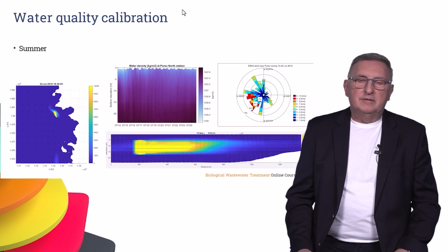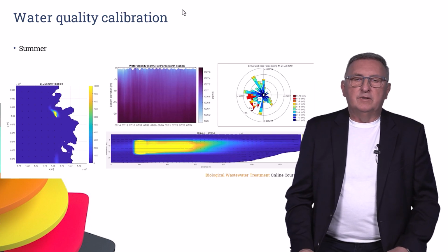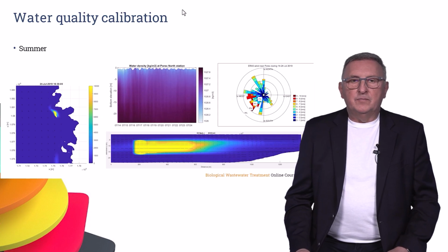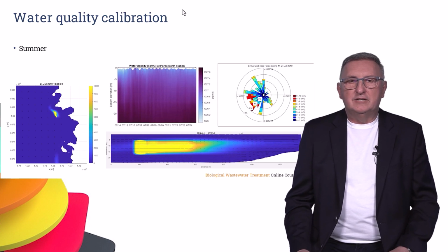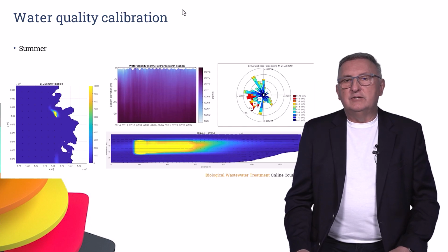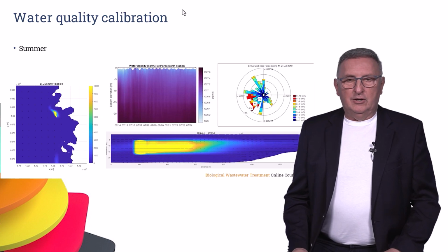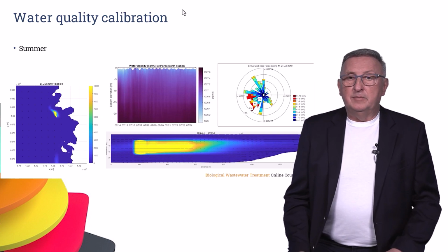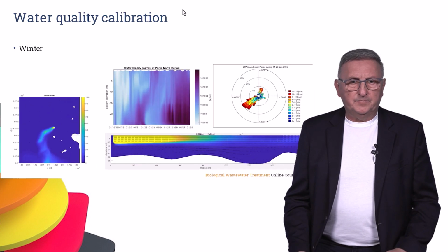They are suppressed by the stratification, where we have a warmer part of the water on top and the colder part of the water underneath. This is quite a sharp stratification, which actually helps additionally in this case. That was one of the reasons that even without wastewater treatment plants, in summer we could not observe much bacteriological pollution on the beaches at the surface, because pollution was kept under the surface at a level of up to 3 to 5 meters.